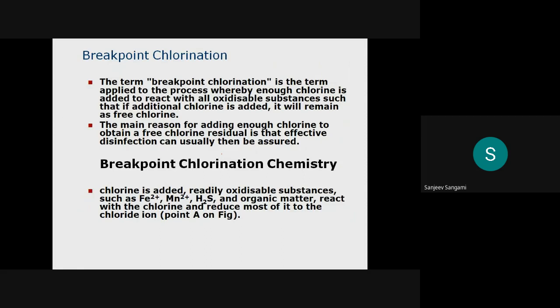So, breakpoint chlorination. The term breakpoint chlorination is applied to the process whereby enough chlorine is added to react with all oxidizable substances, such that if additional chlorine is added, it will remain as free chlorine. Okay. And this we will cover with the diagram itself.